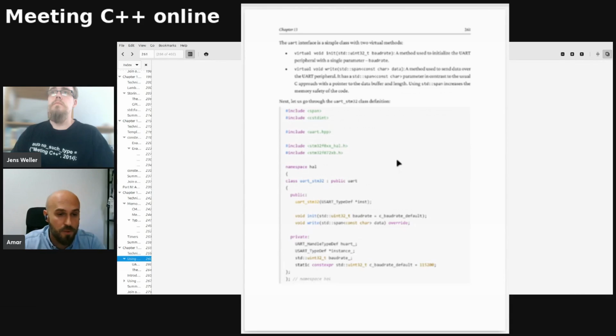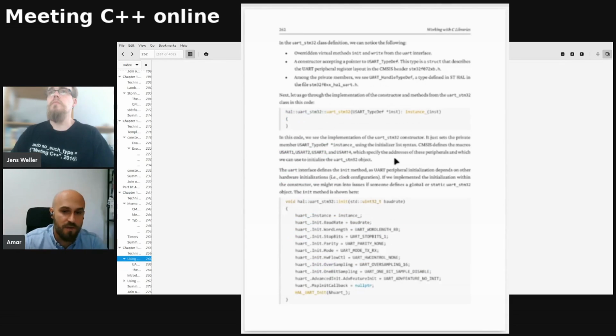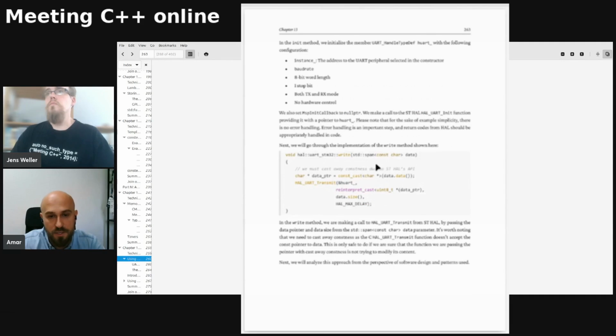And in order to communicate with that accelerometer, we need to use, let's say, an I2C interface. So for that accelerometer, we can write a class that depends on an I2C interface, which is a wrapper for the actual implementation for a specific hardware platform. And it basically shows you how to decouple things and how to use C++ for that. The same can be done, of course, in C, and this is just more about the actual approach in the development itself.